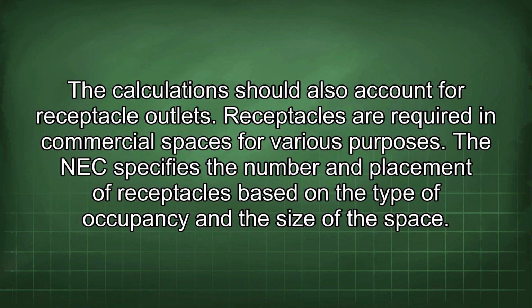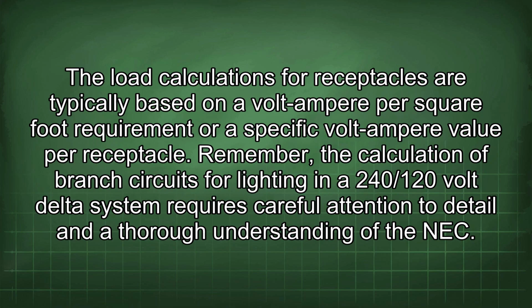The calculations should also account for receptacle outlets. Receptacles are required in commercial spaces for various purposes. The NEC specifies the number and placement of receptacles based on the type of occupancy and the size of the space. The load calculations for receptacles are typically based on a volt-ampere per square foot requirement or a specific volt-ampere value per receptacle.